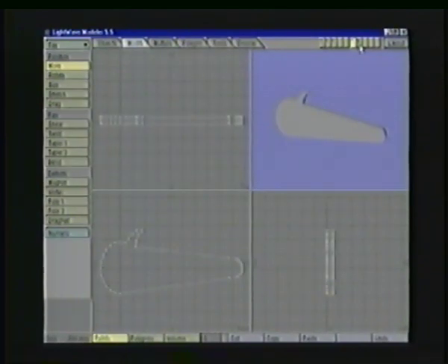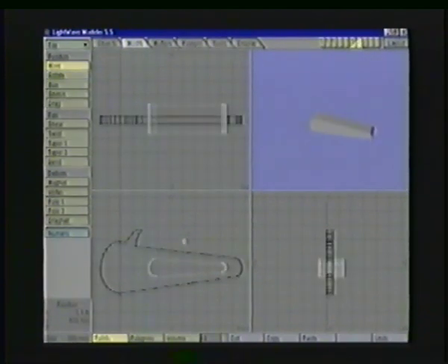Once again, I'll put my cutting tool in the background and I'm going to swap layers with the apostrophe key so that I can scale this down a little bit. So I'm going to go to stretch and I'll place my cursor near the back so that it will stretch toward the rear of the leg as I'm stretching.